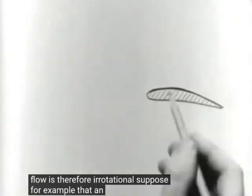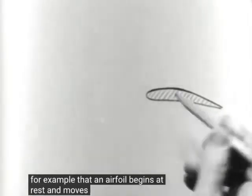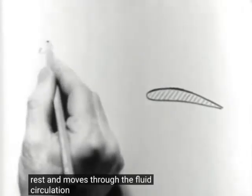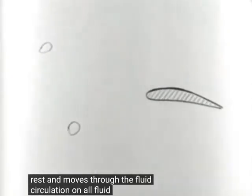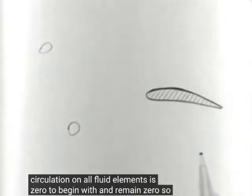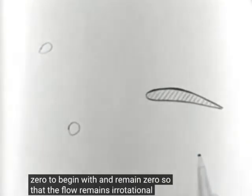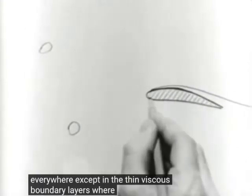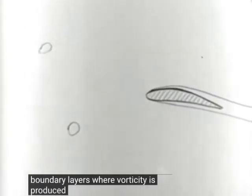Suppose, for example, that an airfoil begins at rest and moves through the fluid. The circulation on all fluid elements is zero to begin with and remains zero, so that the flow remains irrotational everywhere, except in the thin viscous boundary layers where vorticity is produced by viscosity.